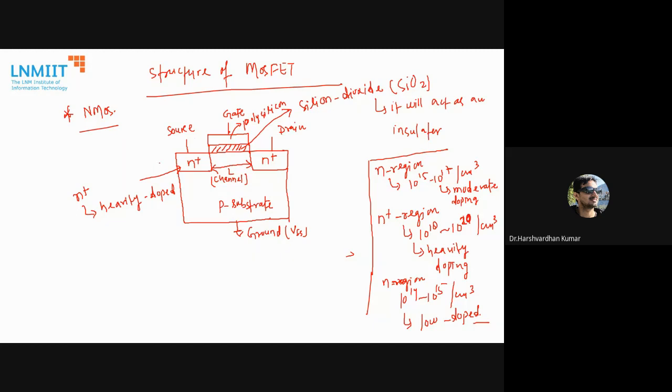Okay, so this is the structure. We can see here an N-type MOSFET consists of a source and a drain, that is two highly conducting N-type semiconductor regions, which are separated from the P-type substrate by reverse biased PN diodes. A metal, or polycrystalline or polysilicon gate covers the region between the source and drain, but it is isolated from the semiconductor.